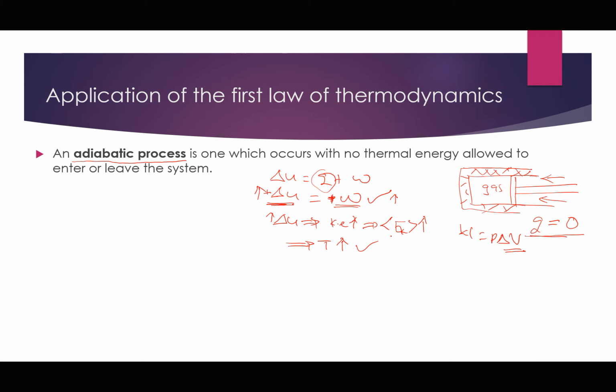But because of the rapid pumping, the brisk pumping, you didn't allow the gas to lose its thermal energy to the surrounding. So the thermal energy went on accumulating. Even though there was no insulation, an adiabatic process has occurred. In fact, in thermodynamics, we would call it an adiabatic compression. So, work is being done on the gas as we pump rapidly, but there is no time for heat being lost, yet work is being done.